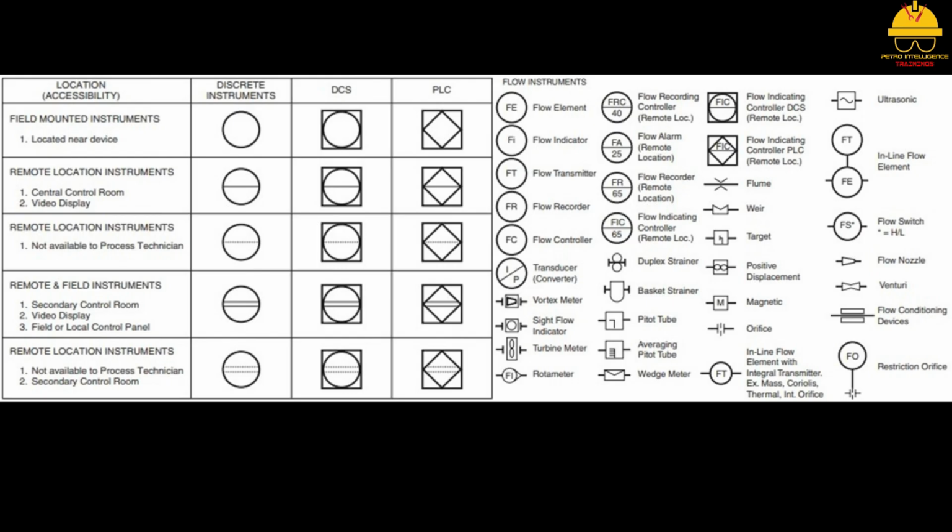In pipes where the diameter suddenly gets smaller, pressure will increase at the inlet point. Fluid velocity will increase through the narrow passage, resulting in a pressure drop. Bends in the piping will cause the liquid to become turbulent. Turbulent flow tends to transfer heat energy better. Another set of factors that will affect the velocity of a fluid is density, viscosity, and temperature increases or decreases.